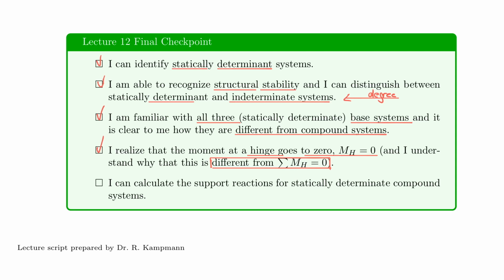Last but not least, we used our newly gained knowledge to actually calculate support reactions for these statically determinate compound systems. And I hope you understand that the mathematics in this class, or the procedures in this class, do not allow us to go beyond determinate structures, right? So we can, of course, deal with compound systems, and we can deal with any determinate system, but we cannot deal with statically indeterminate systems.